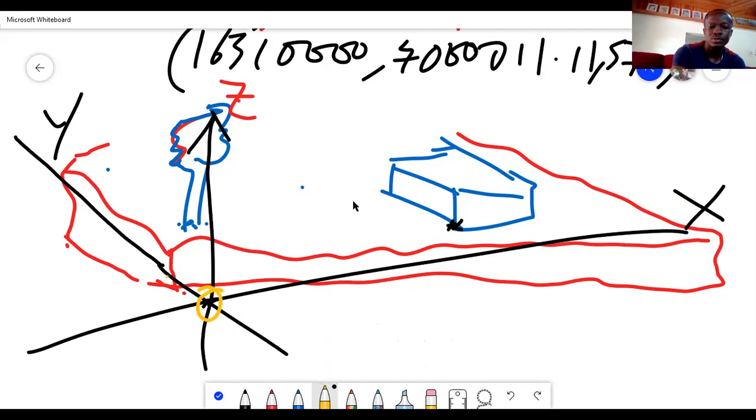So the distance we measure from here to here, that will be X, and this point, maybe XP. So from here to here is XP, and then from here to here is YP. Now, what is the Z coordinate? ZP. So ZP is going to be with reference to a datum. The datum is a reference surface, so we can just draw some dashes to represent it.